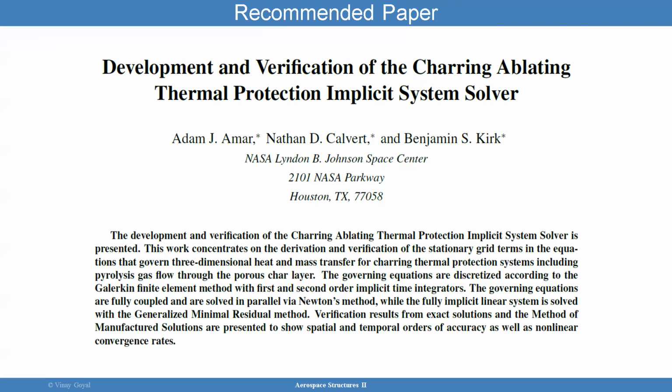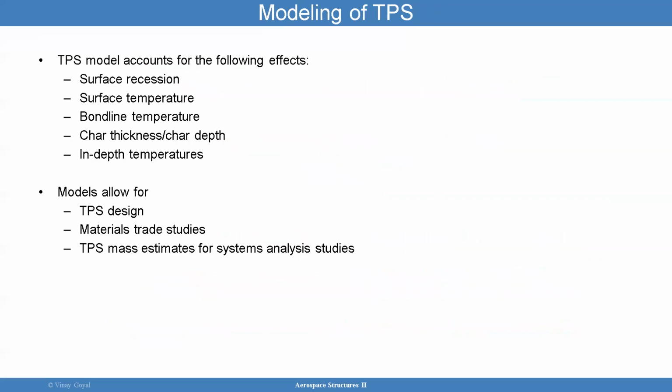And we added a time-dependent problem, which we need to for this kind of problem, and we can then solve it. Basically, we can time march the solution moving forward or backward difference, but you have to really look at the temporal and spatial behavior of the solution, because this is very important when sizing a structure.